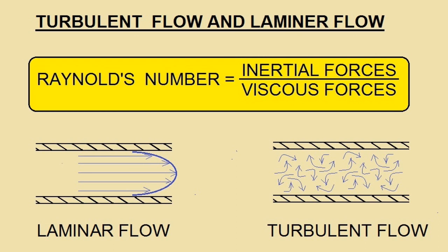In turbulent flow, fluid undergoes irregular fluctuations, or mixing, in contrast to laminar flow. The speed of the fluid at a point is continuously undergoing changes in both magnitude and direction. Turbulence is measured in Reynolds number. Turbulent flow is marked by higher Reynolds number, and laminar flow is marked by lower Reynolds number. For efficient heat transfer, turbulent flow is the best, but erosion is higher as a result.